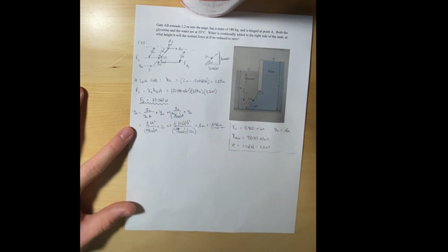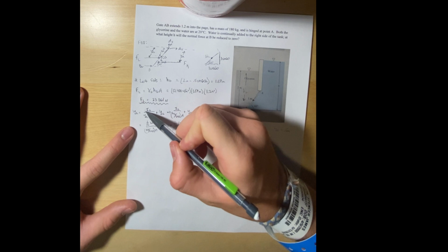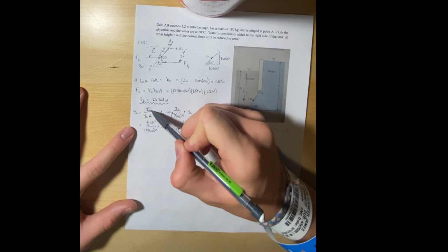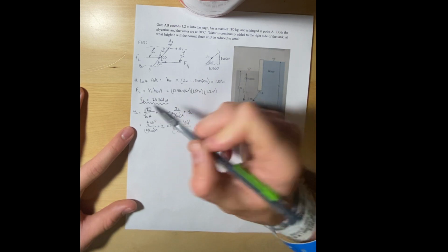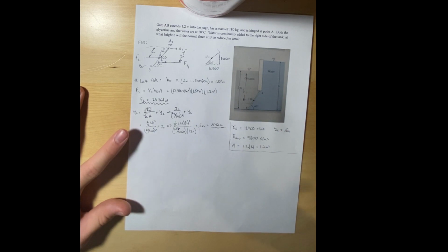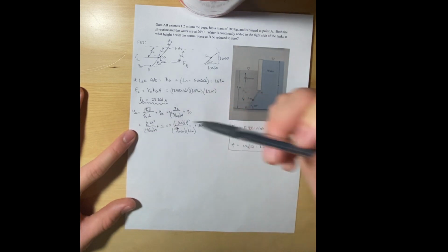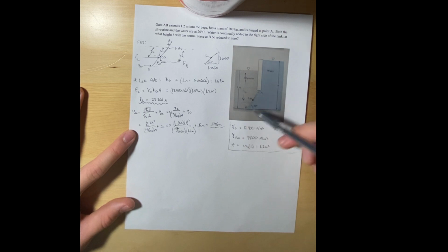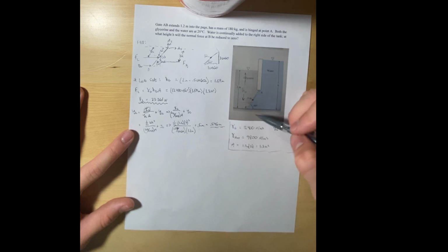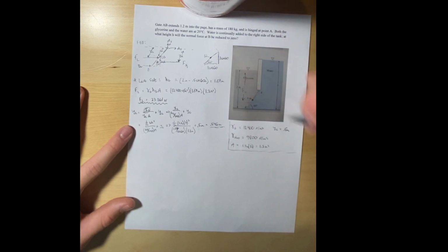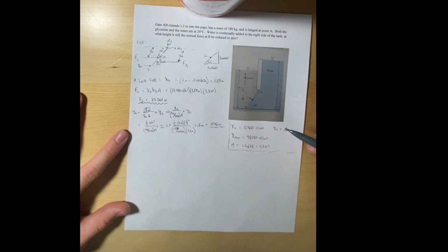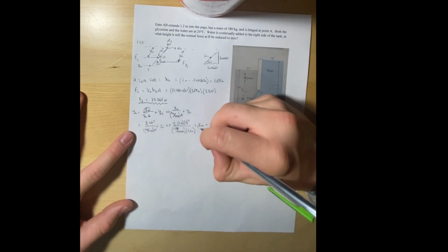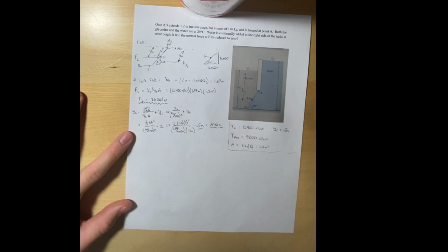Going back to this I sub c term, we can just clarify this up real quick. This is just the moment of the gate, which is a rectangle in our case. So this is base times height cubed, base is just going to be our 1.2, which is the depth into the page, which you can't see in the picture, and then the height is just going to be our 1 meter. And then this y sub c term that we got as 0.5